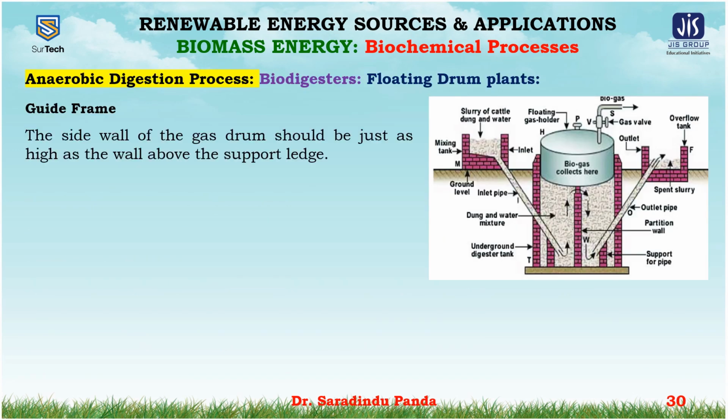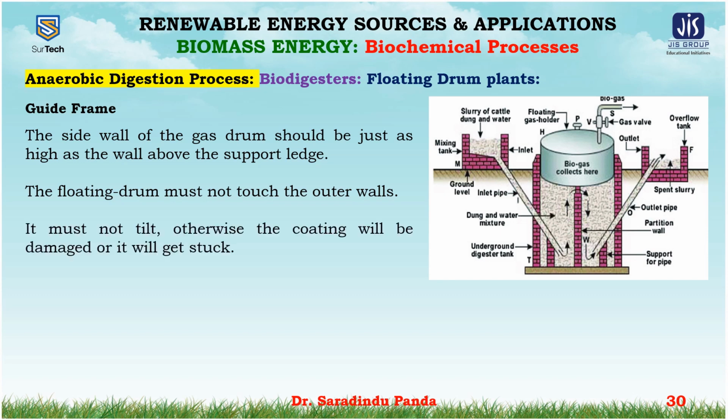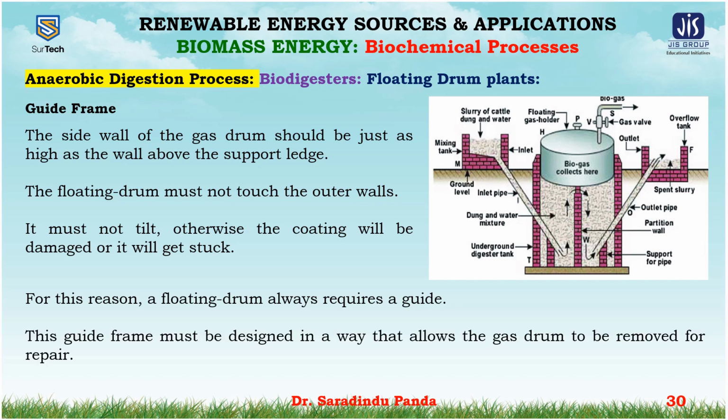Now come to the guide frame. The guide wall of the gas drum should be just as high as the wall above the support ledge. The floating drum must not touch the outer walls. It must not tilt, otherwise the coating will be damaged or it will get stuck. For this reason, a floating drum always requires a guide. This guide frame must be designed in a way that allows the gas drum to be removed for repair.